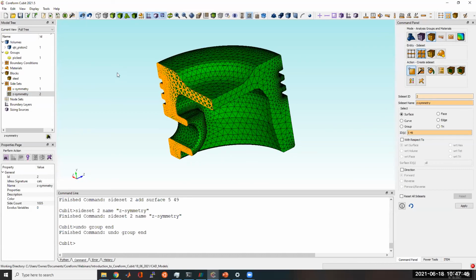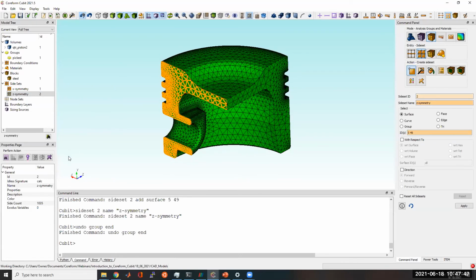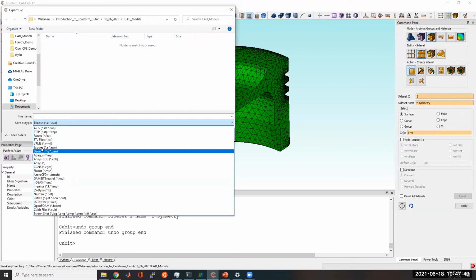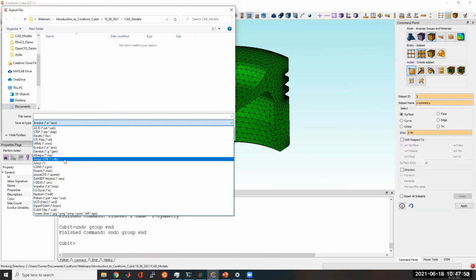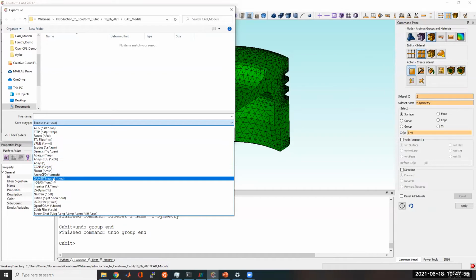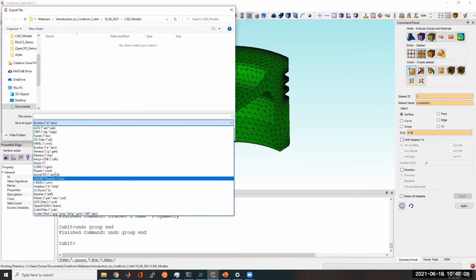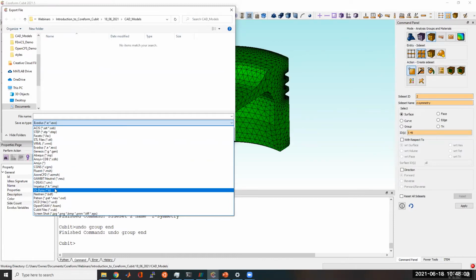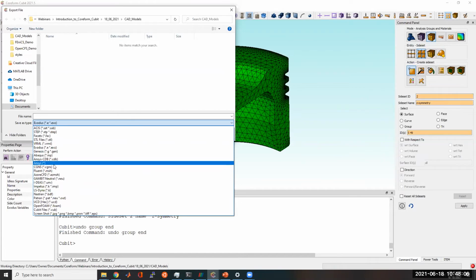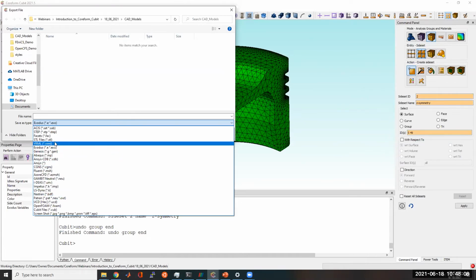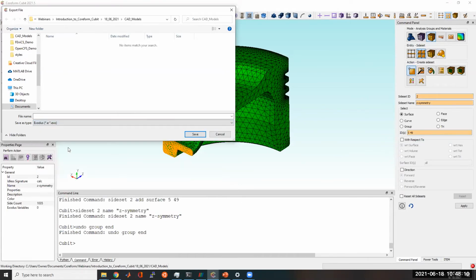You can then export this mesh to a number of different finite element mesh formats. Like the Exodus format, as well as Abaqus input decks, ANSYS CDB, CGNS, Fluent, just a whole list of them, and we're adding more. If there are formats that you would like to see us add functionality for, just send us a note to support@Coreform, and we'll take a look at adding those. But here I could export this to an Exodus file. Call this piston mesh.